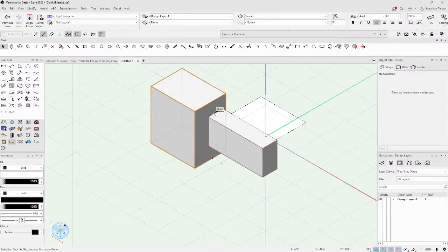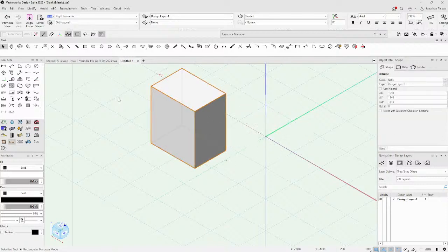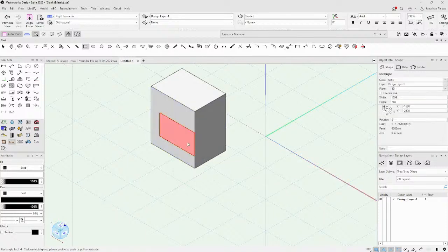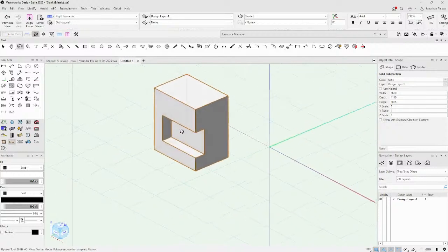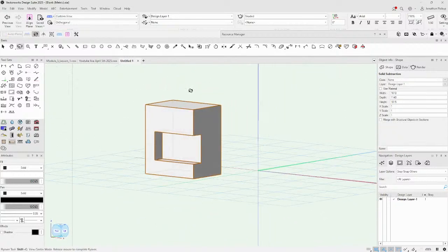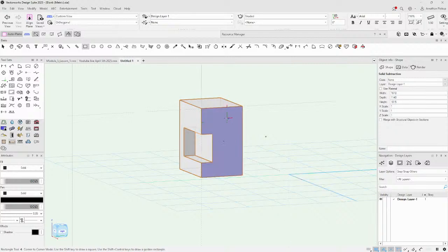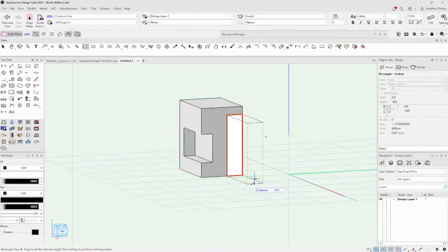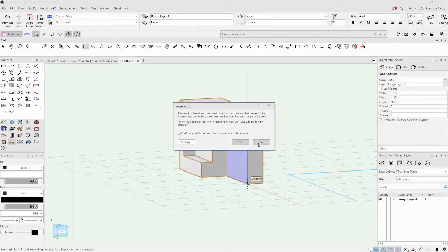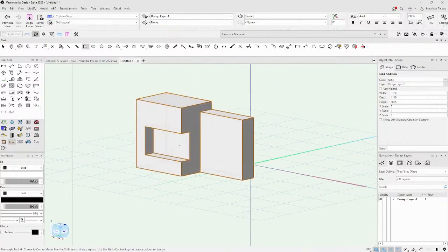So that's not joined to this, and so on. If you join those, if you change that mode to this one, when you draw those objects and you go into the object that you started in, it's instant solid modeling. That subtracts solid. If you click here and you bring it out, then it's instant add solid. And that can be really quick.